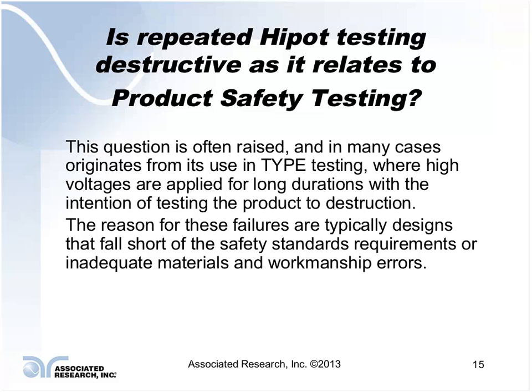It may be related to doing maintenance testing, where you try to test the product at the same potential that you used when the product was originally manufactured, and consequently destroyed the insulation of the product. And if you're testing in accordance to that, yes, I would say a Hipot test is in fact a very destructive test.